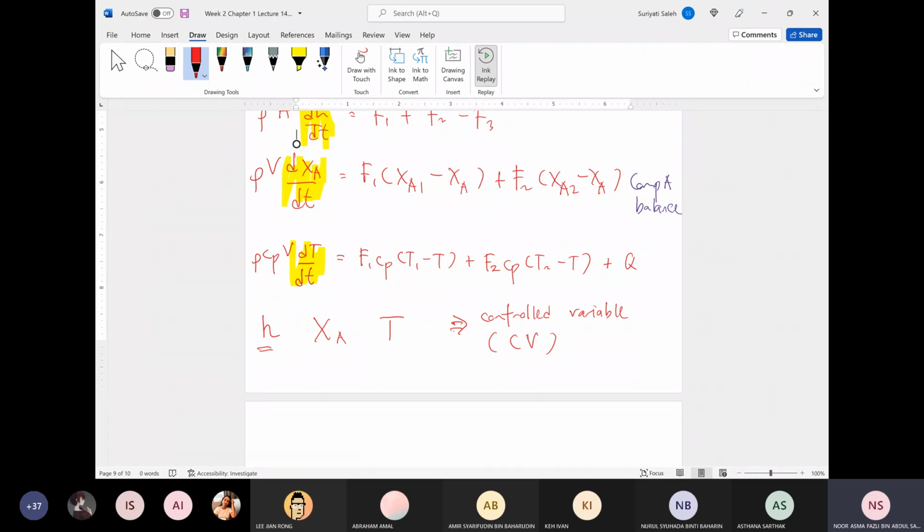And of course, the temperature, because here we put the heater. If we put heat continuously into the system, maybe at a certain point some of your liquid will be evaporated. Or in some cases, if the heat is too low, the temperature is not going to change much. Maybe you want to make sure the mixing process is conducted at 70 degrees Celsius.